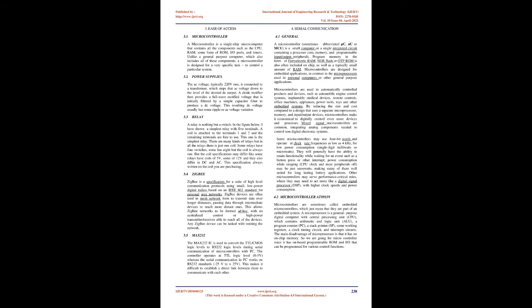They will generally have the ability to retain functionality while waiting for an event such as a button press or other interrupt. Power consumption while sleeping, CPU clock and most peripherals off, may be just nanowatts, making many of them well suited for long-lasting battery applications. Other microcontrollers may serve performance-critical roles, where they may need to act more like a digital signal processor, DSP, with higher clock speeds and power consumption.